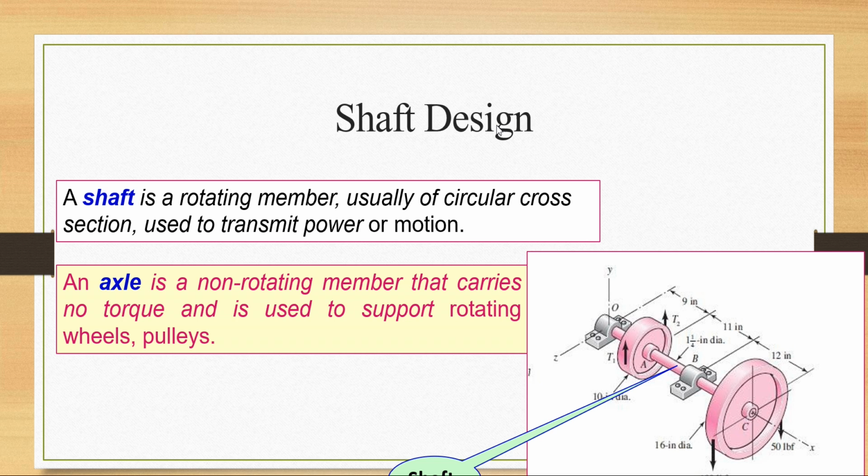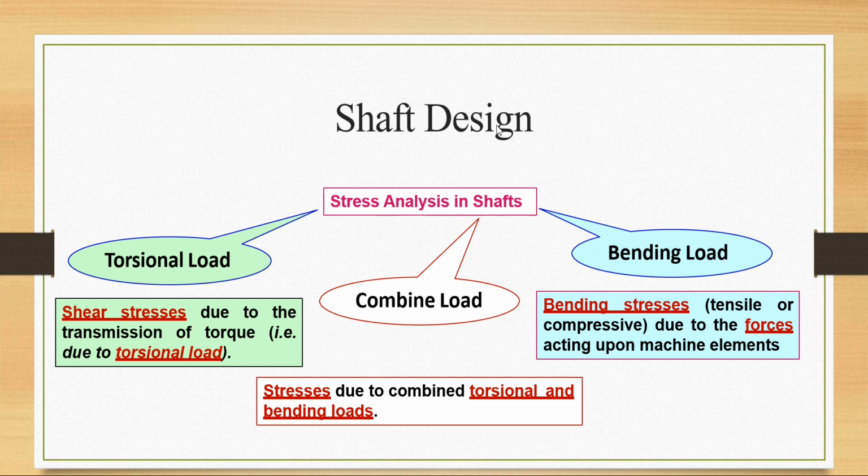As we have discussed, the slide suggests this. The shaft can also be subjected to a torsion load individually. It cannot be subjected to bending load only, because bending is applied due to the elements mounted on it, and generally when this happens, the shaft is rotating. So you can have a case where there is only a torsion load, and a second case where we have both kinds of loads.